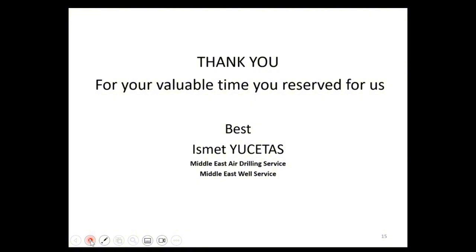It can be brittle enough to break, and you can lose it and drop it in the well. That is the point: you should be careful, since CO2 could make certain materials brittle. But our secondary string, the coil tubing, is an ally. It is good for CO2 injection, but still you should be careful, especially close to the surface. Okay.